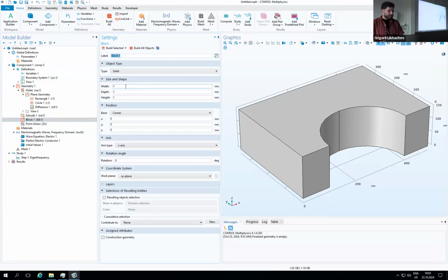It has to have a width of A because we want it to be flush with the unit cell. It can't be larger. Otherwise, after we put the periodic conditions, we are going to have a hole between this unit cell and the cladding, right? So the width is going to be A, that is the pitch.